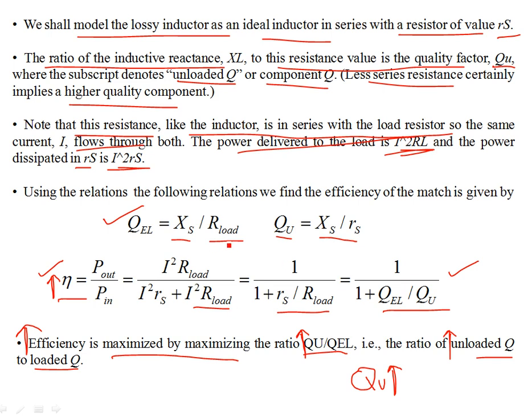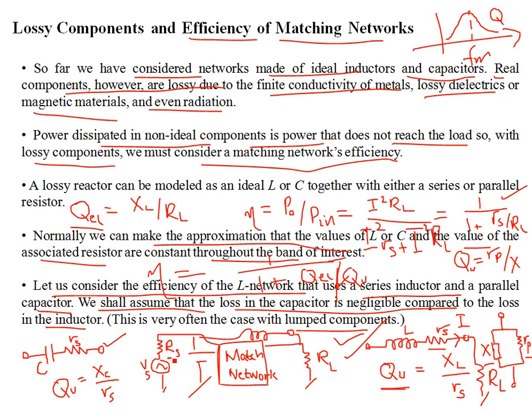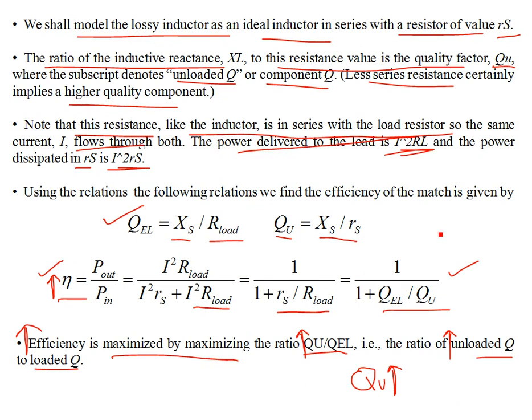The difference between the load and the source resistance defines the match Q. For example, in the previous videos we talked about how the quality factor of the match can be expressed in terms of R high or R low. R high could be either the load resistance or the source resistance. So this is the square root of R high over R low minus 1.